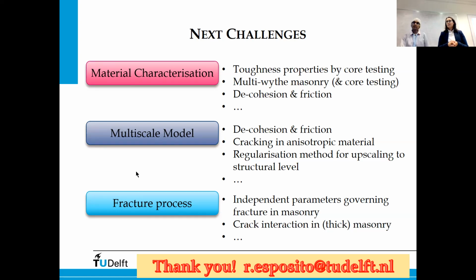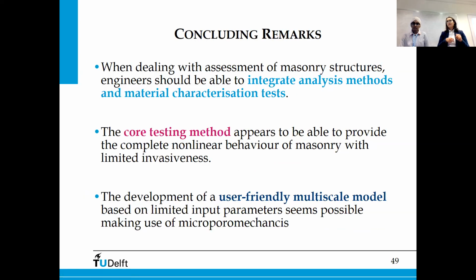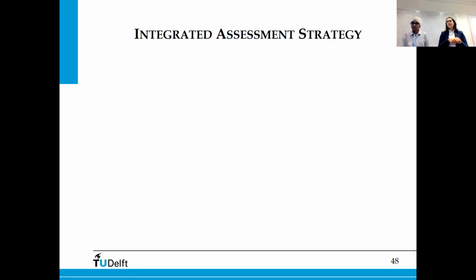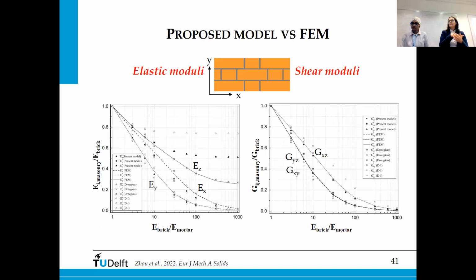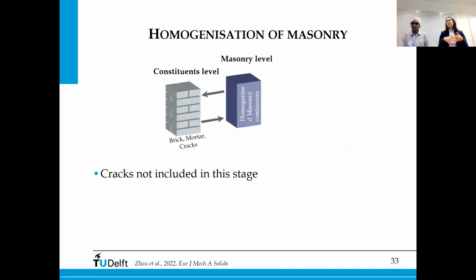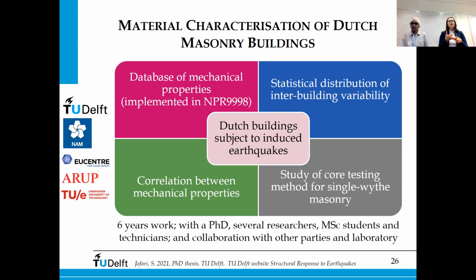Clearly you will have done it with fresh mortar, not with the original. But how does that correlate with your core test? The correlation for the core test was both from field-extracted samples and from replicated samples. We didn't make a distinction there. We also took some data from literature and previous tests that have been done on replicated masonry.